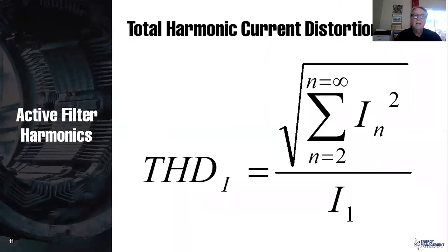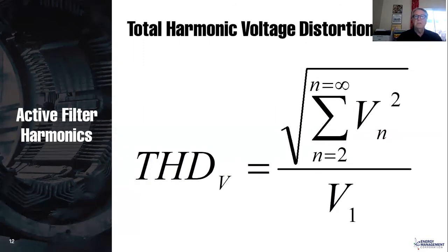Now, if I take that 100 amps and I multiply by 30% and I get 30 amps, that's still okay. It's not exactly accurate, but I'm in the ballpark. And so for the most part, if I'm not trying to get to very accurate numbers, that still kind of works. And I can still use 30 amps, and the 30 amps is conservative. So the actual harmonic distortion will be slightly less than that. How much less will depend upon the level of distortion. Now, harmonic voltage is exactly the same formula, you just use voltages.